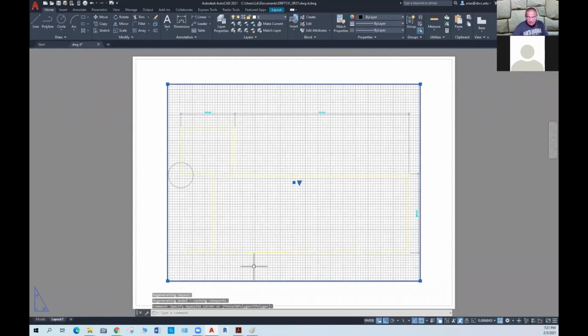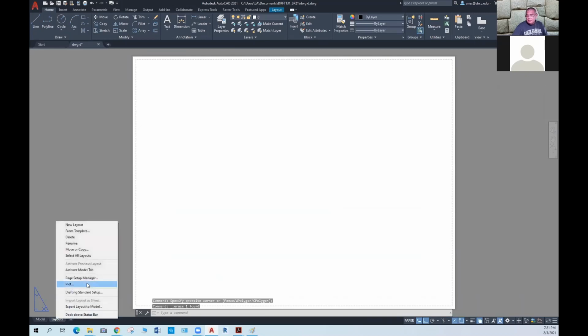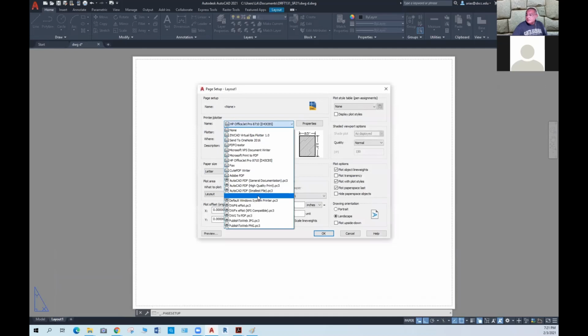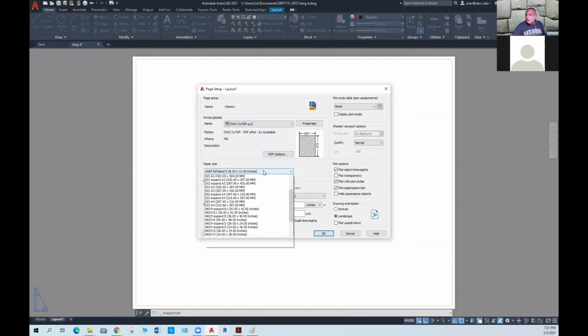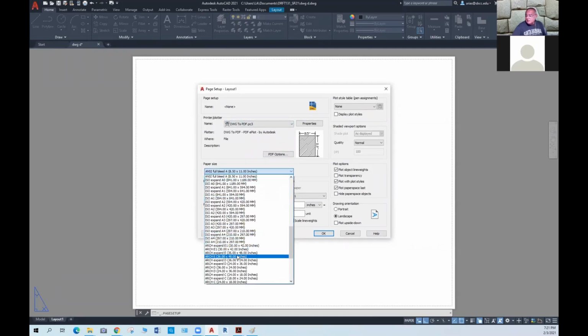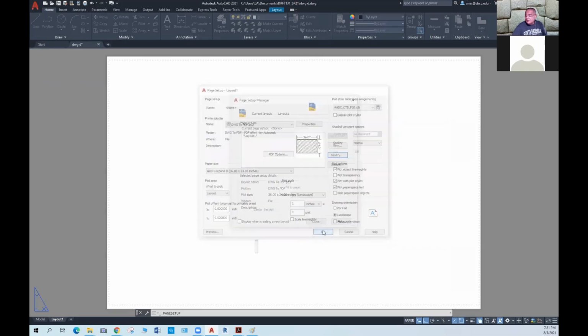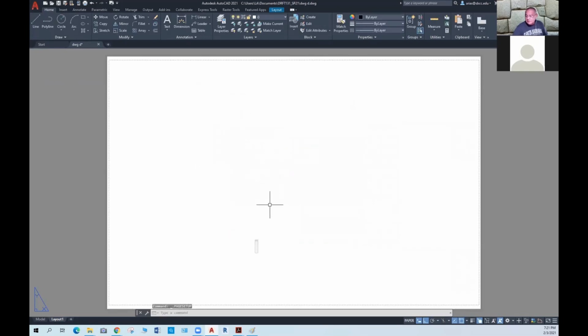And so remember, delete that, do paste it up, modify. We're going to select PDF. I'm going to select architectural C, and then layout, and then my CTV, right? That's pasted up. And so the first thing I'm going to do now is to insert my title block.